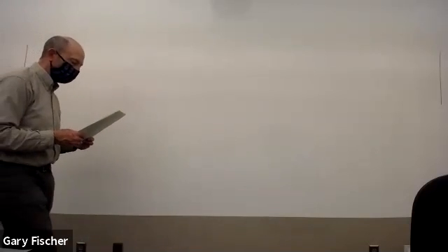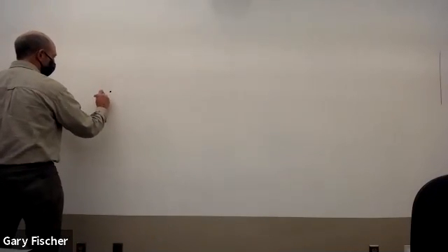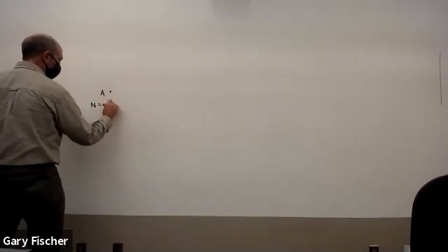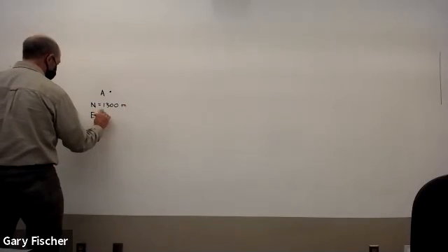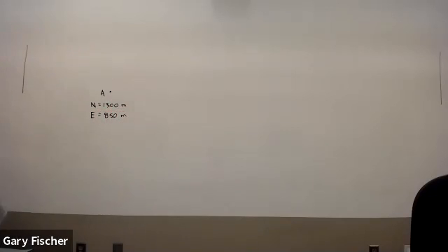So in problem 6, they ask you the north and east coordinates of point B for the situation shown. They give you 2 of those, and then they give you some more information related to it. Okay, so A is over here. This is A, and it has a northing of 1,300 meters and an easting of 850 meters. If you imagine a grid, and let's say your origin is right there, and you go up a certain distance to get to northing, and then you go east a certain distance to get easting, your dot would hit right there.